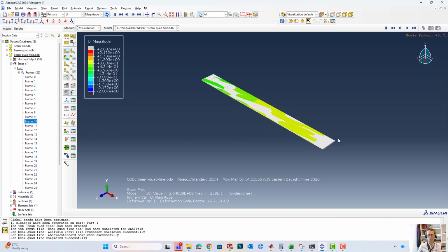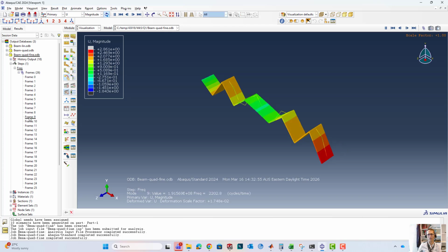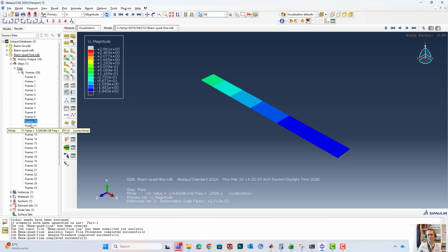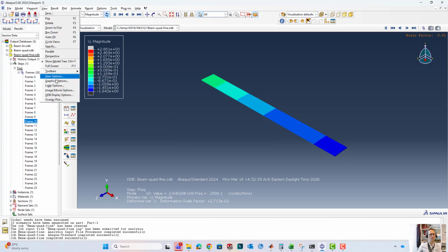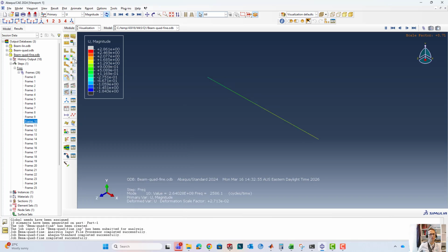You see now that these longitudinal mode frequencies are in a different position relative to the other bending modes. See how much higher we got in with the bending modes compared with the first resonant frequency. I have to turn off the rendering to be able to show the material deformations as these shapes present themselves. Now you can see we get an arrow at each of the nodes. We've got 11 nodes now, whereas before we only had 2, so we get these arrows. And that's our higher order bending modes.